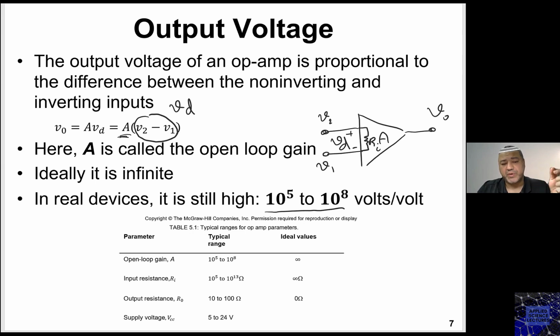One of them is called positive, non-inverting, and the second one is called inverting input, right? They are connected across an input resistance that is called Ri. This Ri is extremely high, which means that the current going into this Ri is very small. And we'll talk about the usefulness of this.